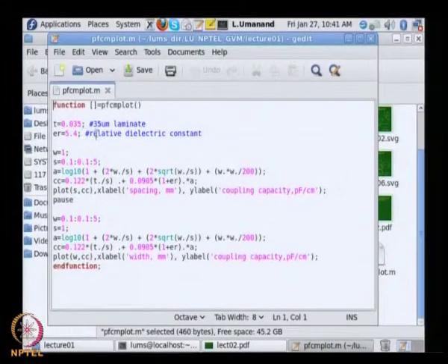Basically, it is the same equation that I just put a few moments ago. Look at this, which I shall probably mark for your benefit. This is the same equation that I had been discussing, 0.122 into t ./ s. Now, let me tell you why I am using dot slash, dot plus 0.0905 into 1 plus ER, which is epsilon r.